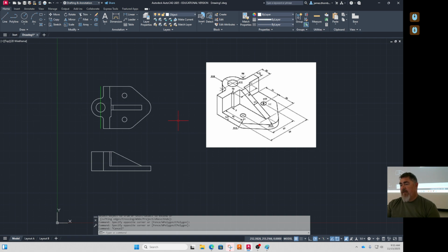Does that make sense? So do we need the right side view on this? Is it going to give us anything new? No. So we could do it just for practice. But it's not going to give us any new things. So I'm going to not do it. Because when we're picking views, we want to use the least amount of views needed to fully describe the part. The right view is not going to add anything new, and that's going to take a bunch of time doing it this way. If it was in 3D, like if we're doing it from Fusion or SolidWorks, making that right side view would be 2 clicks, right? But if we're doing it manually, not worth the time for it. Yep.